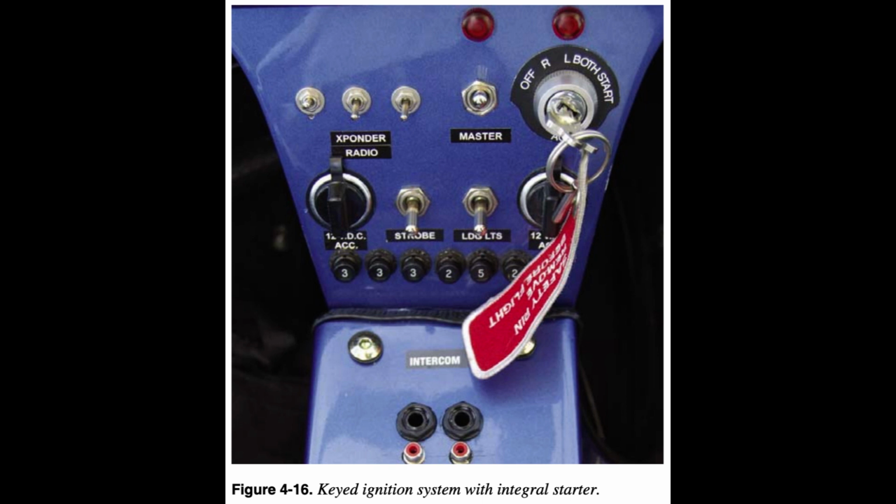If the engine stops running when switching to one ignition system, or if the RPM drop exceeds the allowable limit, do not fly until the problem is corrected. The cause could be foul plugs, broken or shorted wires between the magneto/generator and spark plugs, or improperly timed firing of the plugs because of a defective control box. It should be noted that no drop in RPM is not normal, and in that instance, the aircraft should not be flown. Following engine shutdown, keep the ignition switches in the OFF position.